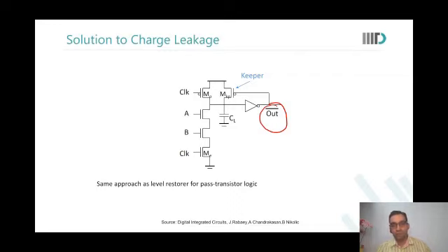Charge leaks from A and B, the transistors that have A and B connected to their gates. No, actually the charge is provided actually. Yeah. So ineffectively the power that was lost due to leakage, that will be lost, but now the source is different basically. So leakage you cannot reduce. You're not reducing leakage. Just saying that the impact of leakage on the gate and its reliability has been mitigated.